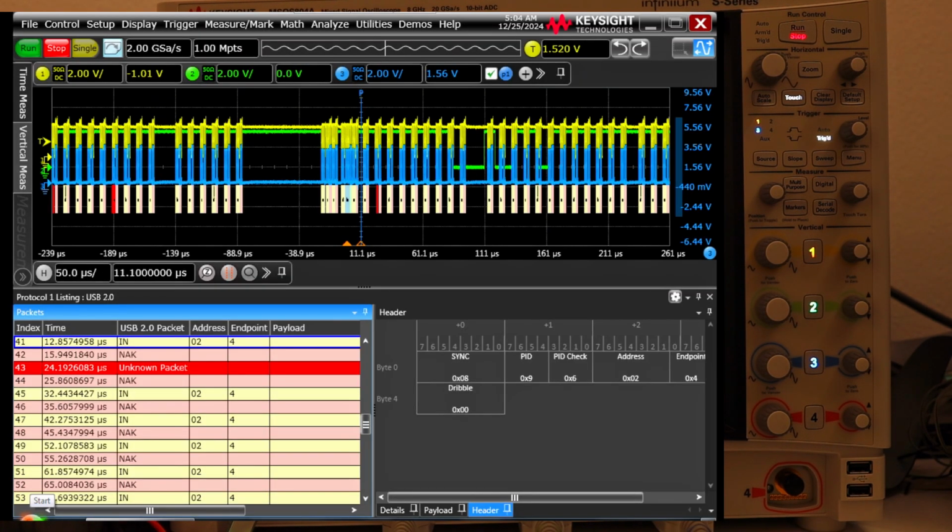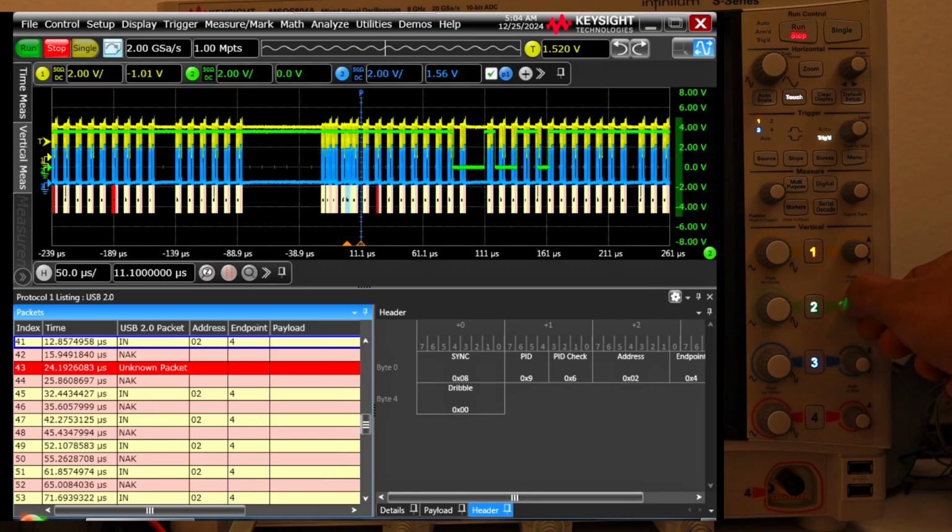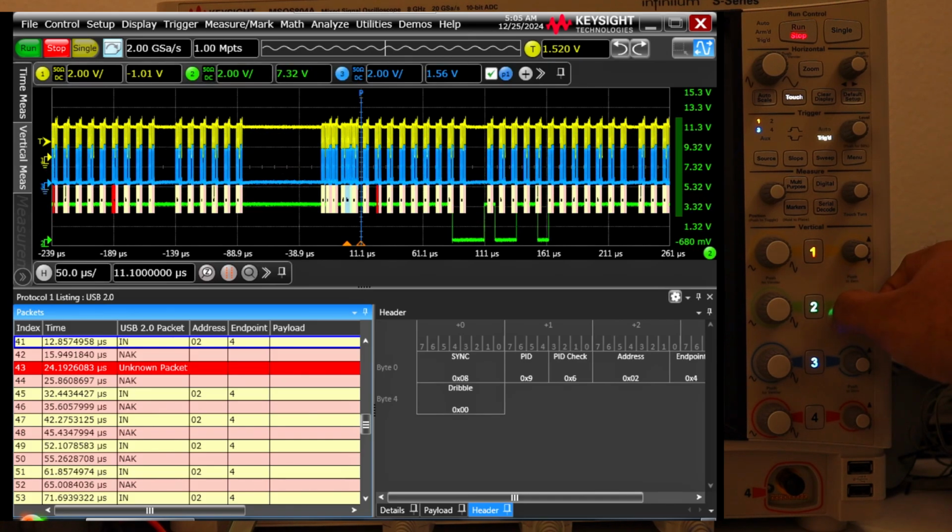On your screen you can see there are 3 channels being activated: channel 1, channel 2, channel 3. Channel 1 and channel 3 are connected to USB, and USB is currently configured as shown in MDA 3000 and a USB full speed, and it's connected to my TI dev board. And I'm also probing on channel number 2 the UART signal. Maybe I'll show you. Bring it in the front, and this is the UART signal.